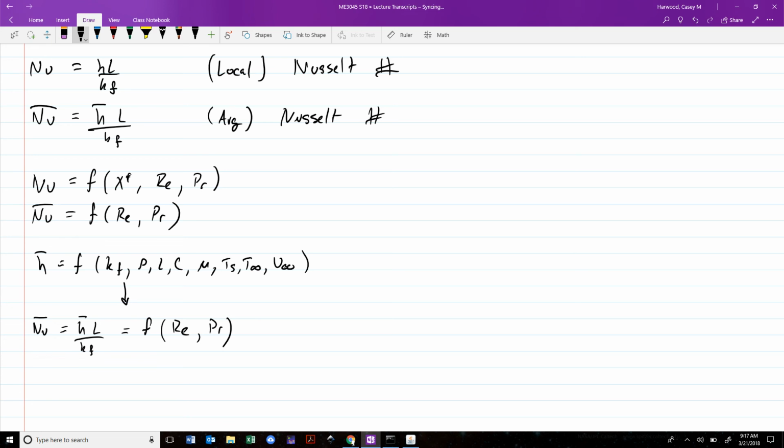On the other hand, if we were to recognize that all of that important functional relationship has been boiled down to this by non-dimensionalizing our governing equations, our experimental design now only has to include 2 independent parameters, which means if we want to do 5 treatment levels, we end up with just 5 raised to the 2, or 25 experiments, as opposed to 5 raised to the 8th.